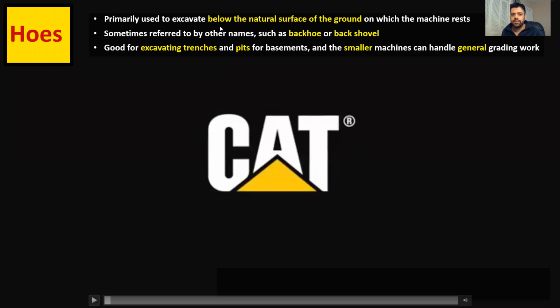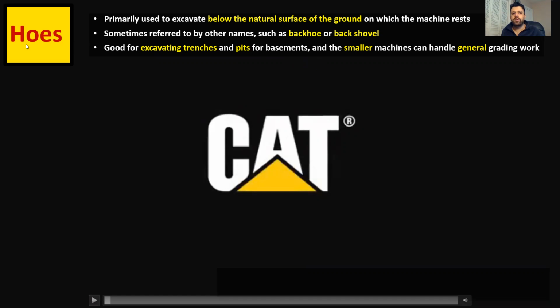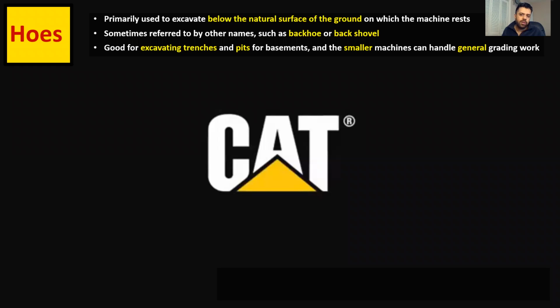Hoes are good when you're doing excavation below the natural surface of the ground where the machine sits. So you can easily dig below the surface. Hoes could also be called backhoes or even back shovels. When you need to excavate trenches or pits, they are superior to hydraulic excavators because they are smaller, so you could more easily use them.